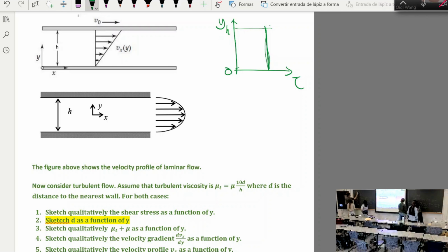I kind of overheard you saying this part. This might be a very dumb question, but how do we actually know that the shear stress is constant here? So basically, by the control volume analysis, there is only shear stress acting on the right. The force acting on the control volume is just the shear stress. So the shear stress from the top has to balance the bottom. Oh, okay. That makes sense. Yeah.